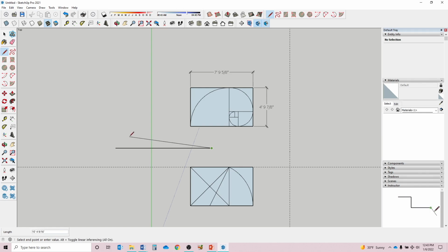I can also do inches. Type in L again. I can say 12, and then when you're putting something in quotes, we're going to use that button for inches. Enter. And let's just dimension these to make sure that they are the desired length. Perfect.